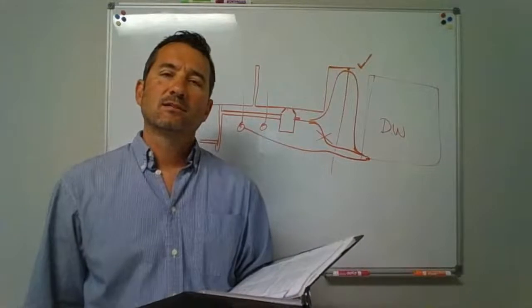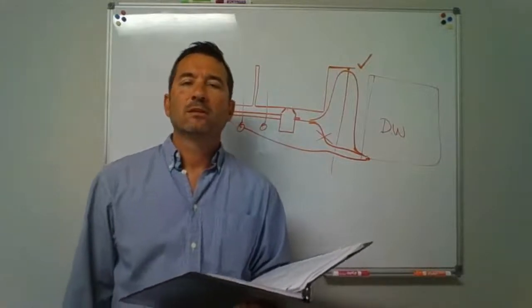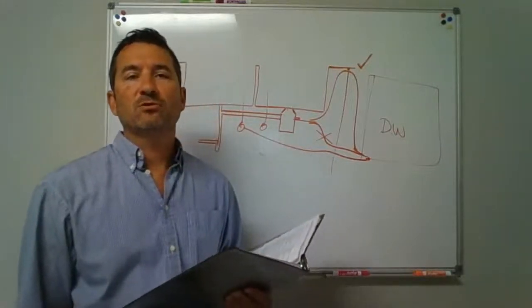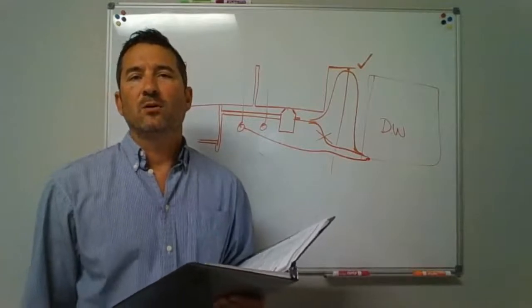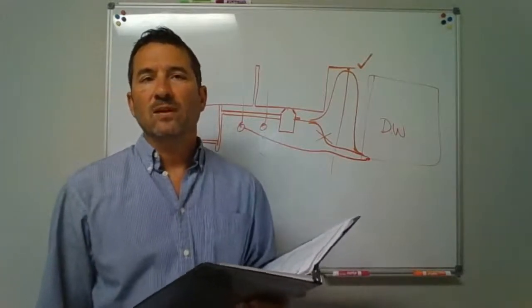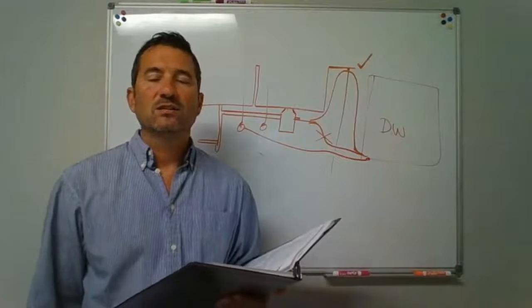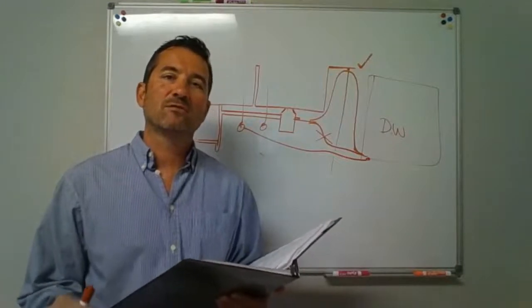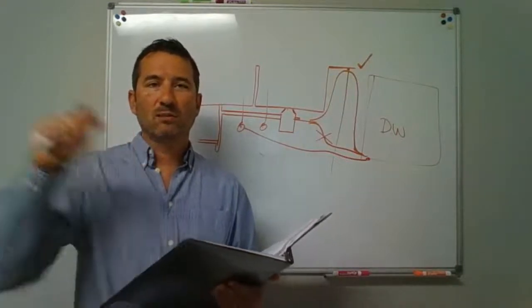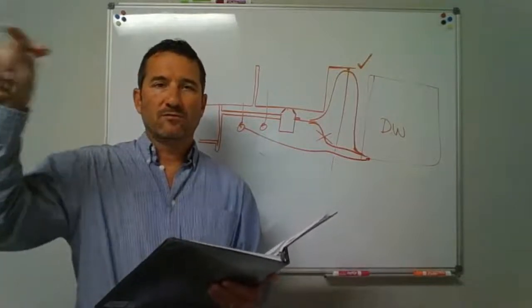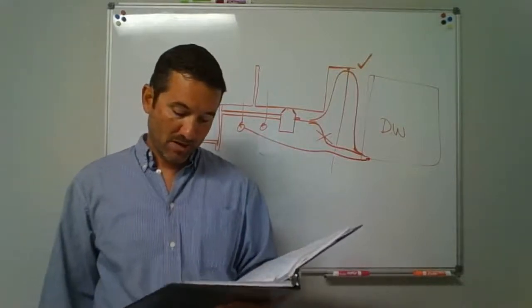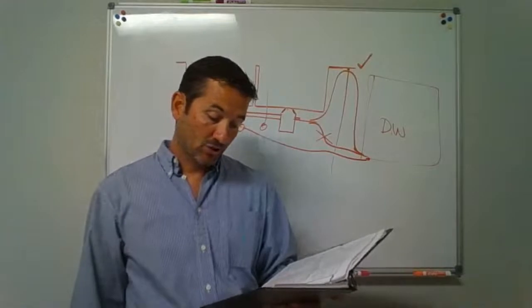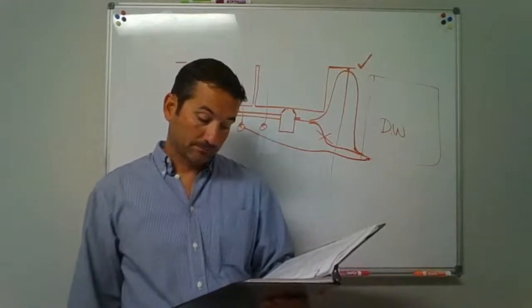That term ought to ring a bell. That was one of your questions from Chapter 2 quiz as far as what is developed length? How do you measure developed length? It's along the center line of the pipe and the fittings. Okay, so not point A to point B, but you got to follow all the turns that the pipe makes and measure all that up.